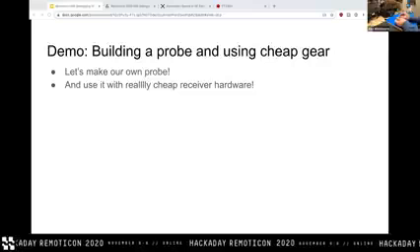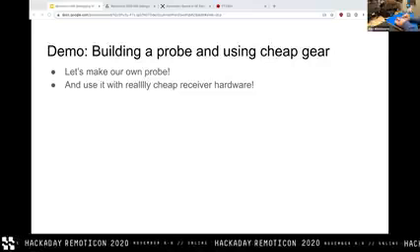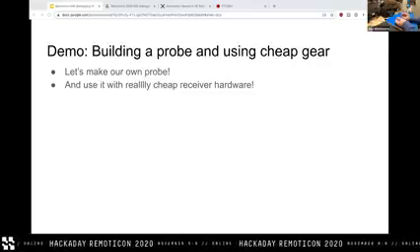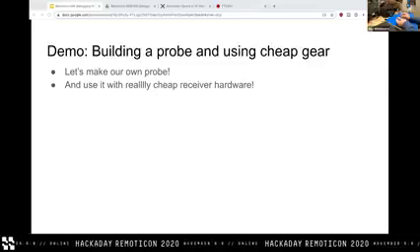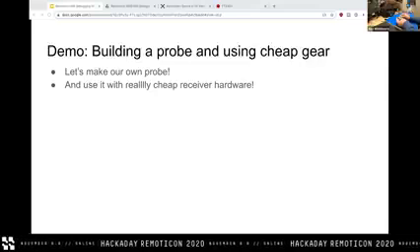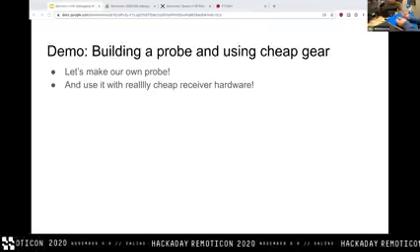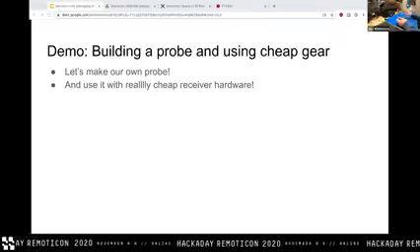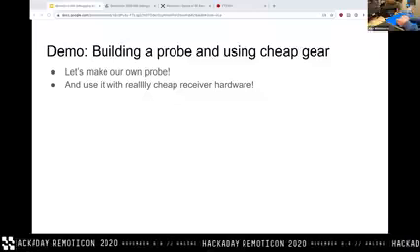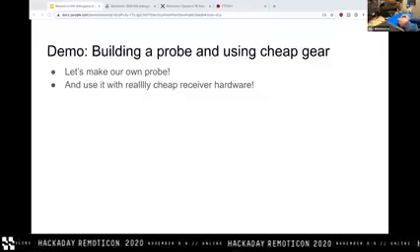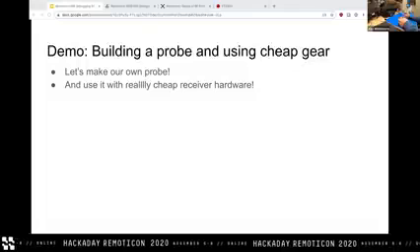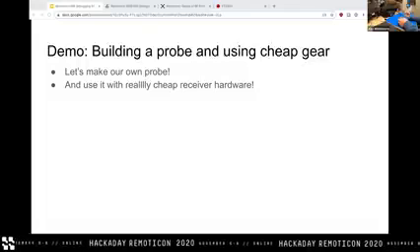The LNA has a DC blocking capacitor on the RF input side, so that no DC voltage from the power supply circuitry of this guy leaks out into your antenna or anything like that, which is important because these are DC shorts to ground.